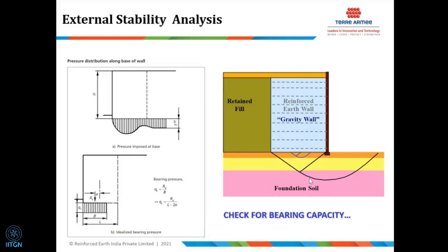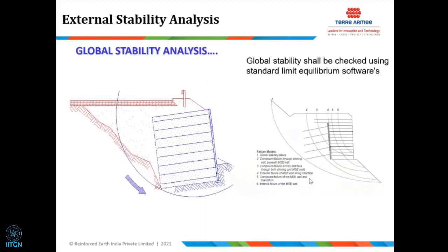And hence, the bearing capacity that we'll get by using Terzaghi's equation vis-a-vis a plate load test, there will be a huge difference. So there is no point in doing a plate load test and checking the bearing capacity for RSW. If you really want to check, you can do a confirmatory borehole, and you can use the equations again, and then you can check it. And that's proven. It doesn't require any kind of research on this topic.